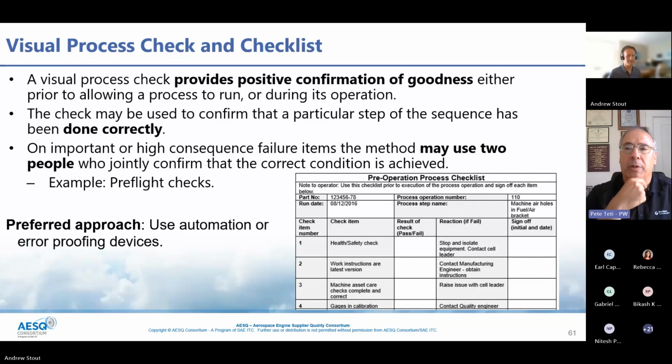How do you mistake proof to know that that bearing is not left? How do you ensure a dust cap is not buried inside an engine? How do you check that an O-ring has been installed before you assemble something? These are all examples, but that one just came up recently, and an eagle eye is going out to talk with folks doing that type of check about how they are going to assure a visual process check is in place. Thanks, Andrew. That's a good example.